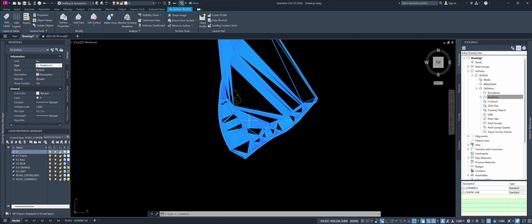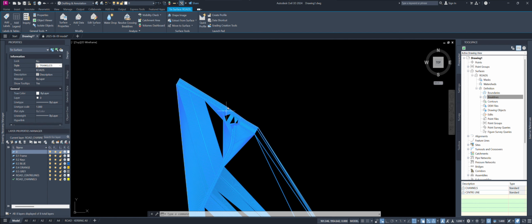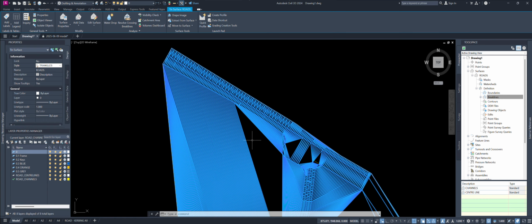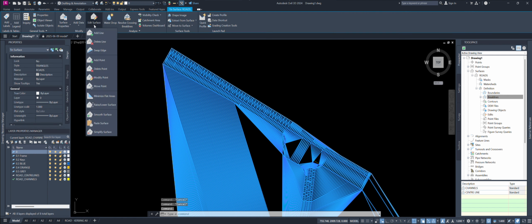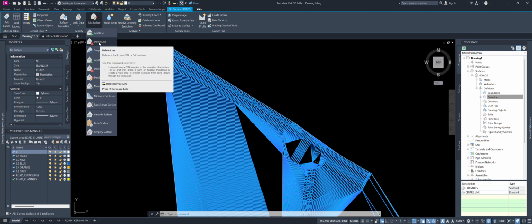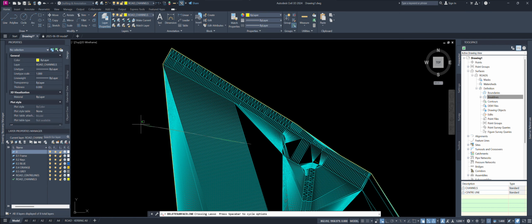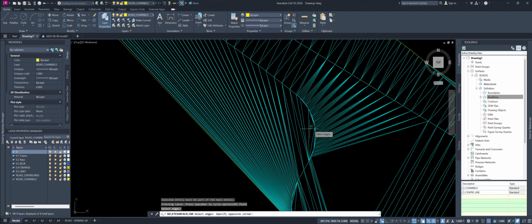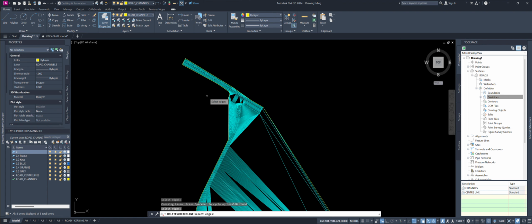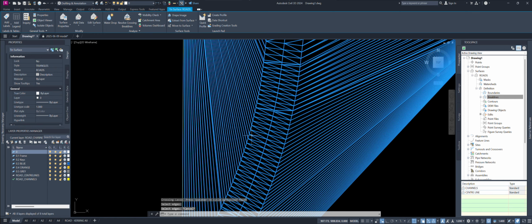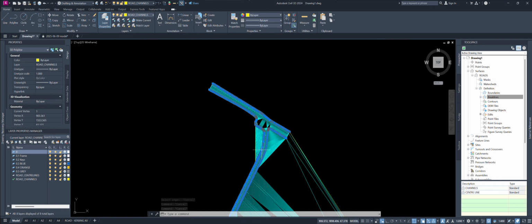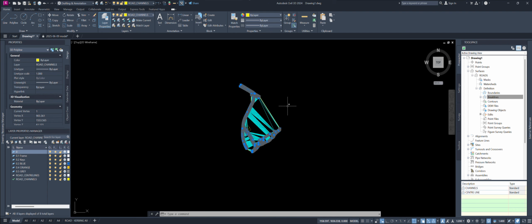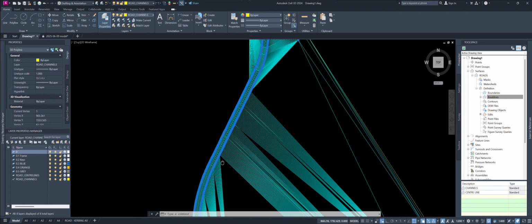Now, this is where the easiest bit is coming, by looping all the models. Instead of me manually trimming all the triangles, I can use the boundary, but this is the manual way. You select your surface, you go to edit surface. Remember, this works only if your triangles are visible, and then you can trim your triangles just like this. But the easiest way of trimming your raw surface is literally by looping your channel all the way around, and that's what we've done.